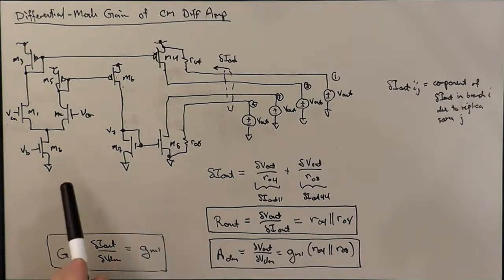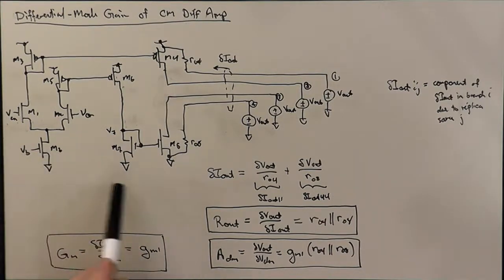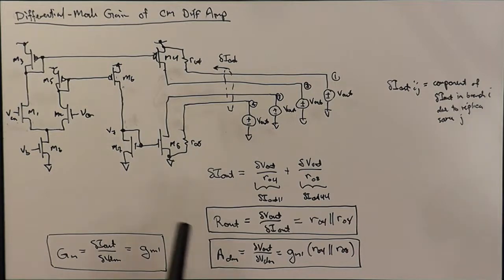Okay, so if I have a 5-transistor diff amp and a 9-transistor current mirror diff amp, and I have the bias level set to be the same place, and the transistors are matched between the two, the NMOSs match the NMOSs and the PMOSs match the PMOSs, I should get basically very comparable differential mode gains, and also common mode gains.